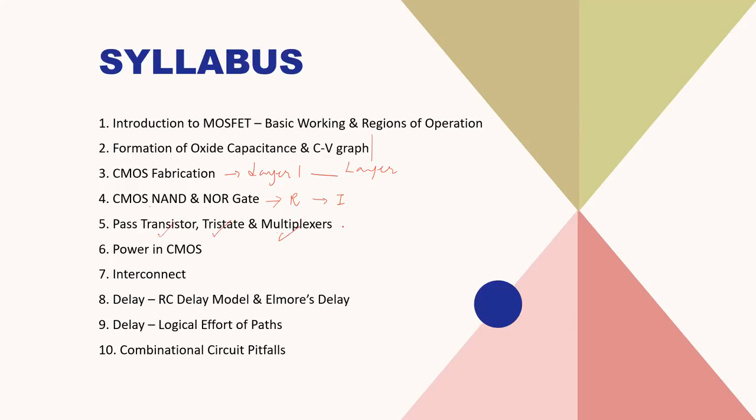So this is one other important topic. Then we will study all the different powers and all the different types of leakages that happen in CMOS, a very, very important topic around dynamic and static power dissipation, which takes place in CMOS. Here we'll see some of the pitfalls of CMOS, and you will also study sleep cycles, or gated MOS. So there will be different ways we can try and save power in CMOS, and these are being realized in the industry as well.